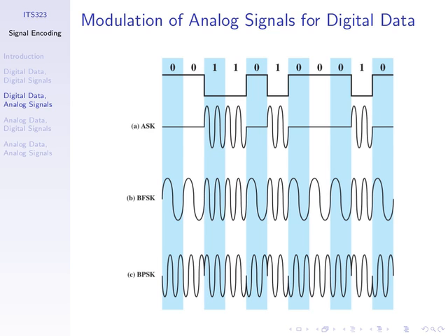We have some digital data at the top that we want to send, and ignore the digital signal there. Here is the output analog signal if we use amplitude shift keying. We could say the scheme in this case is if we want to transmit bit 0, set the amplitude to one level, 0 in this example, keep the frequency and the phase to be the same.